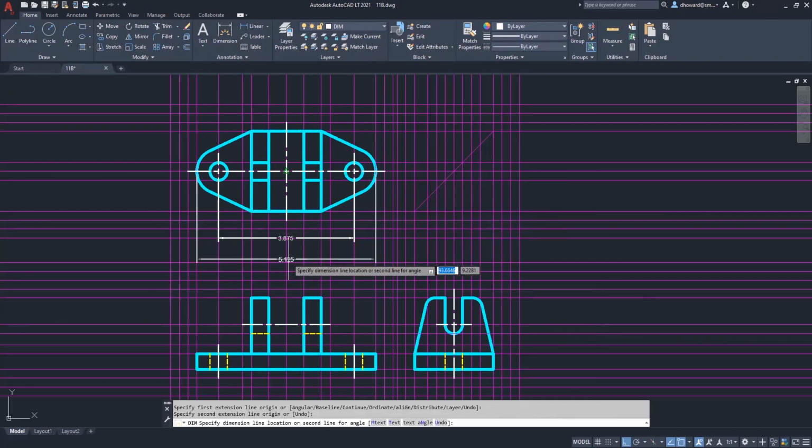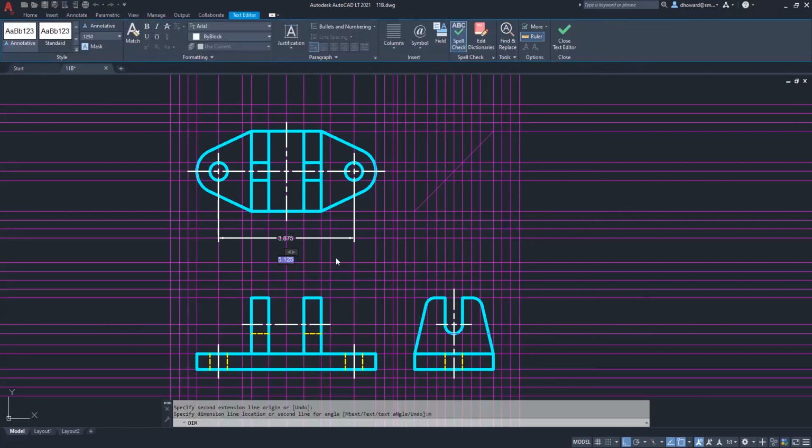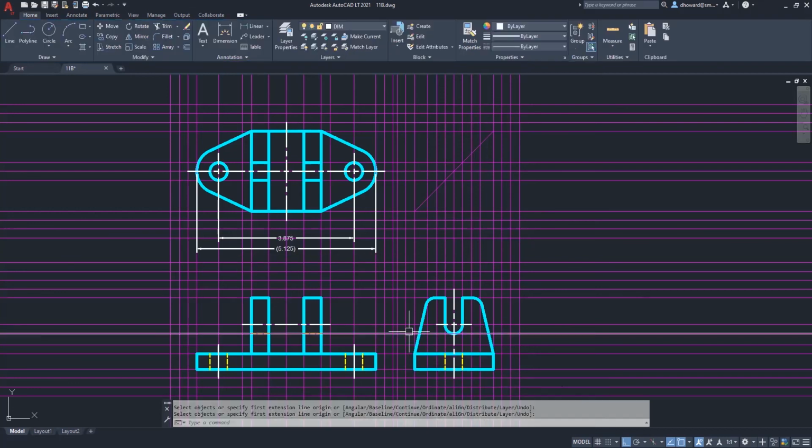and before you place it, enter, you would put a parenthesis mark around the beginning, and then you arrow over to the edge and put one on the outside. And now you can place that guy. So what the parentheses are telling us is basically that this is just for reference. Okay. We'll talk more about that later. But the more accurate measurement is the distance from center to center. Okay, so we got that one in place.